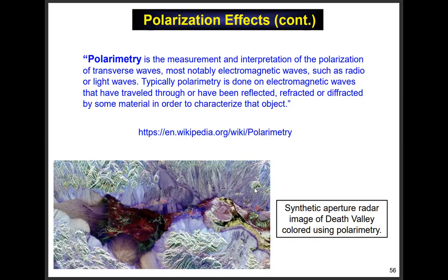And that gives what's called, I think I mentioned this word before, diversity. And so they can take whichever signal is the strongest coming from this pair, right? And so that's what's called diversity, taking advantage of different polarizations to increase the signal strength. Okay. All right. So anyway, any questions on this before I move on?